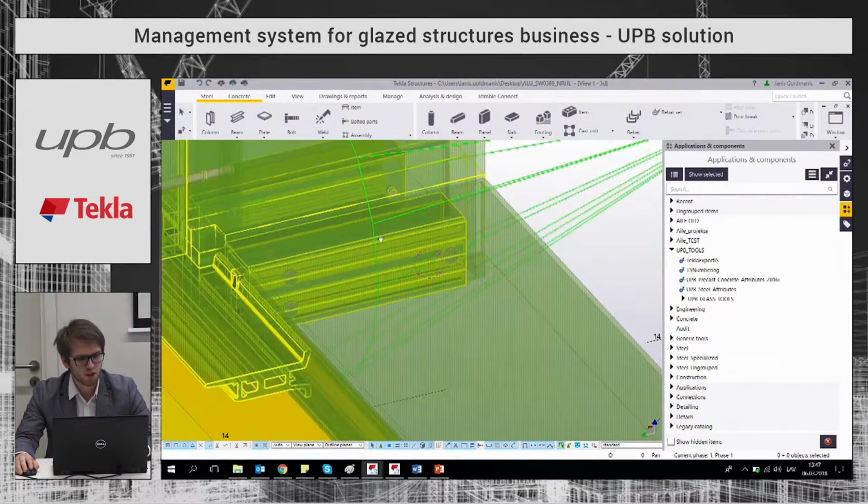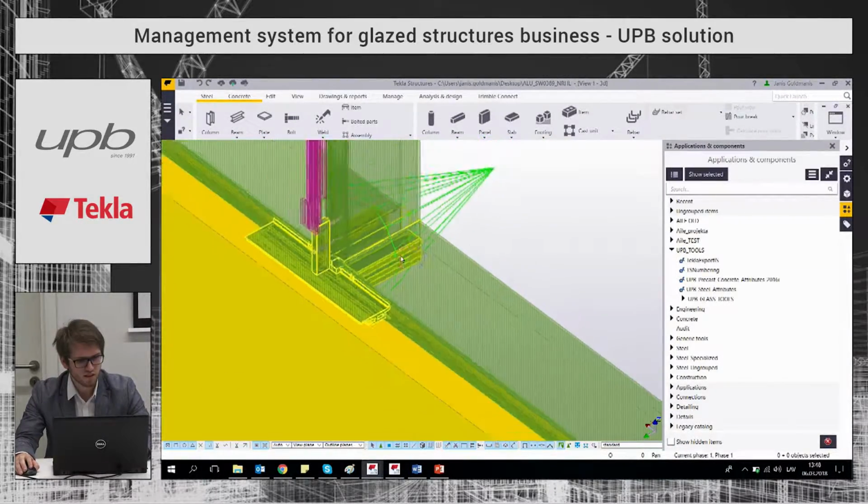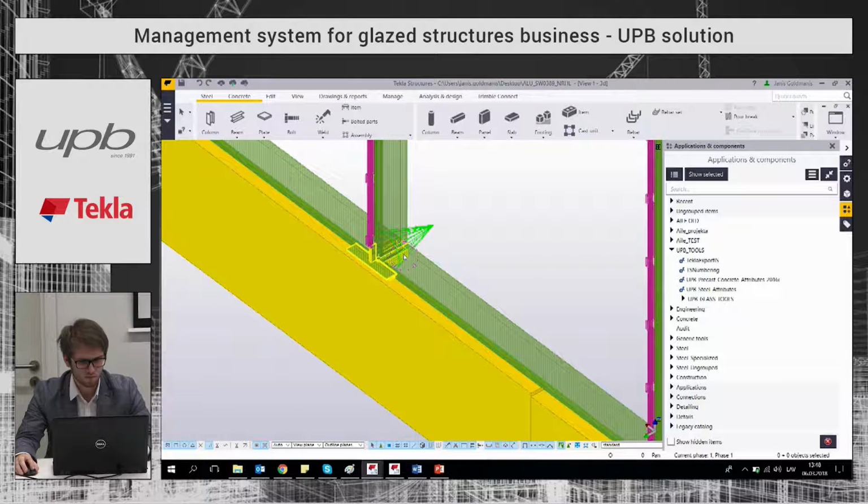So now we try to create everything in Tekla, also including all the holes and bolts, and Tekla can output in many different standards. We have decided that we'll use the STEP file format. Tekla can output this STEP file, and most CNC machines have converters that can convert from the usual popular standards to the CNC machine standard, and most of them should recognize a STEP file.